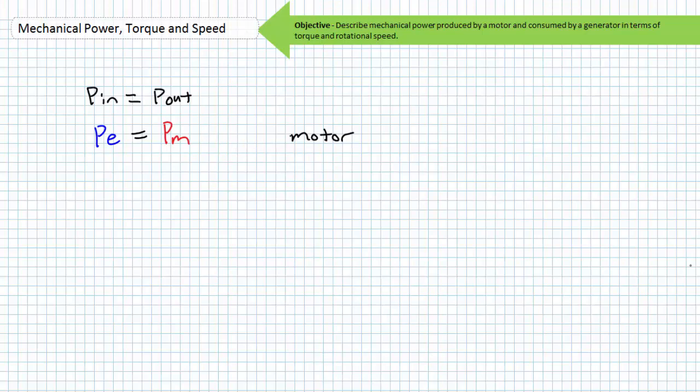If positive electrical power is input to a motor and it supplies positive mechanical output, what would happen if a generator was exporting electrical power and we wanted to keep electrical values on the left-hand side of our equation and mechanical values on the right-hand side of the equation? Sounds like a simple switch of signs could take care of this. We're left with a relationship with a negative sign on both sides of the equation. Although it is a mathematically valid technique, don't be tempted to remove the negative sign because it's an extremely useful indicator of polarity and direction, as we'll find out in a moment.